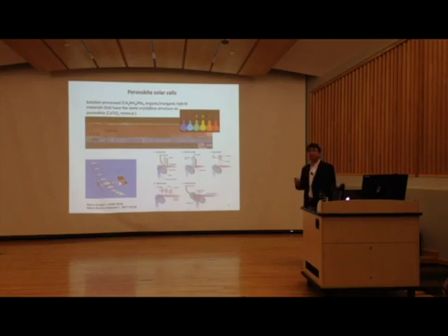Actually, for perovskite solar cell, in research, people use solution processes. Solution process means you can process something like printing papers. For example, this is the way people propose to manufacture perovskite solar cells. There have already been several startup companies in the world trying to commercialize these technologies. And if you look at the thickness of a perovskite solar cell, it's so thin. This is 200 nanometers. So 1,000 nanometers is 1 micron. So the whole thickness is less than 1 micron.